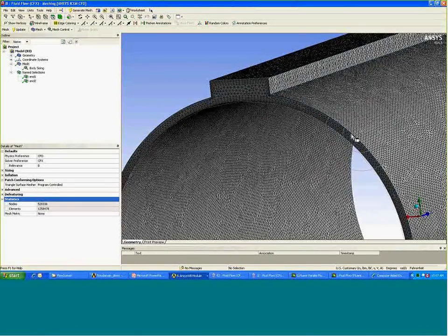If the gap becomes smaller and smaller, like in the current situation where we're looking at a 10 thou or 20 thou gap, then this element count will go up, because the element size to fill in these gaps becomes smaller if you want to use tetrahedrons. Just to resolve that, I could be looking at 6-7 million elements for such a geometry. So that's probably not ideal. So what are we going to do about it?